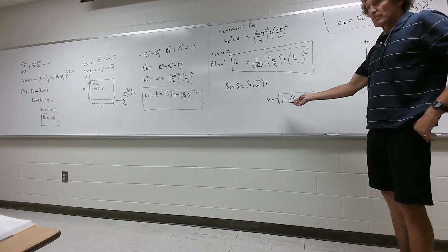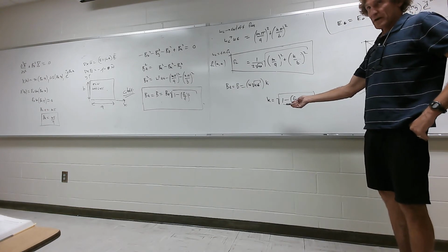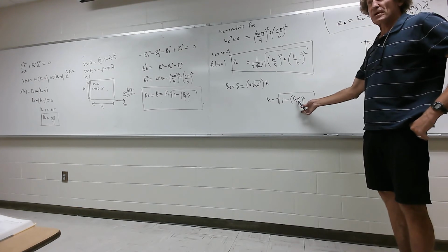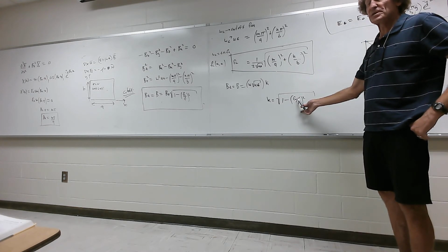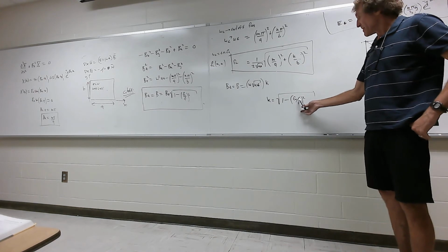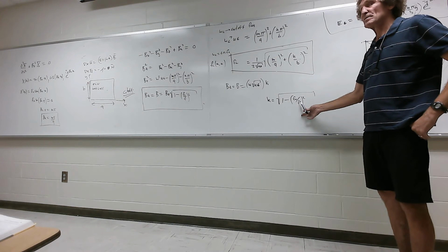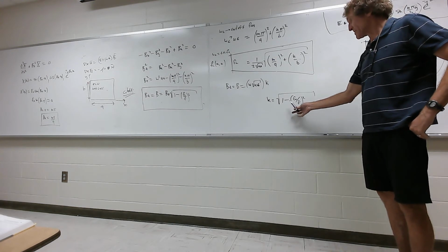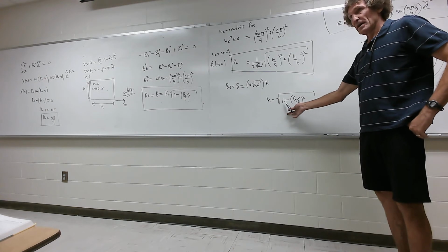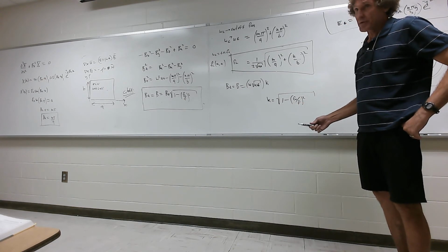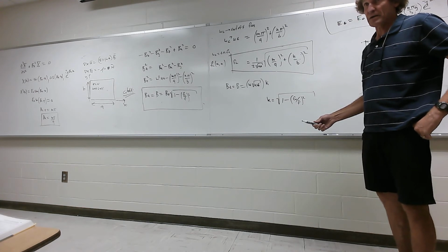Now, this number K we're going to use all the time for waveguides. Remember, FC is a cutoff frequency. Remember what I told you. You have to be at a frequency above cutoff for propagation. Do y'all hear me? Now, look at this. This will always be less than 1 if it's propagated. If it was greater than 1, then this would be a negative number in here, and you would have an imaginary value for K, which is meaningless. Nothing propagates unless you're above cutoff.